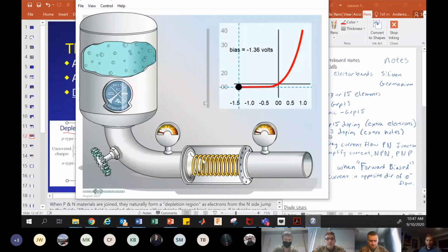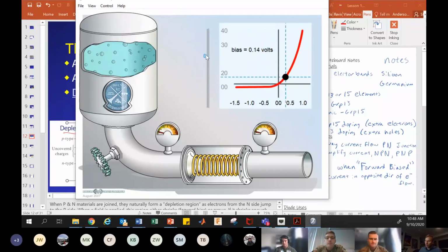It's got a spring that's holding it closed. As you increase the pressure, nothing happens until you have enough pressure to overcome the clamping force of that spring. So you can assume that spring is pre-tensioned. Once you break that threshold, the spring gives way right there.